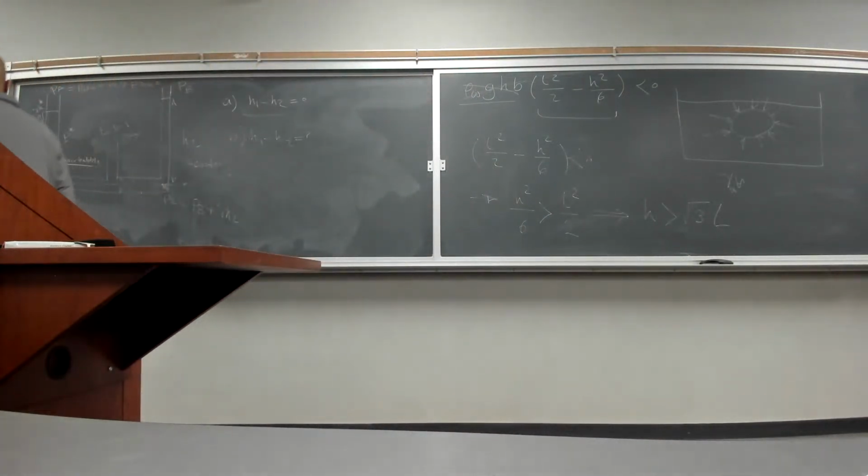Okay. Can we say this air bubble is immersed inside this fluid? It is definitely immersed inside that fluid. So the force that the fluid, the water, is exerting on this air bubble is going to be gamma of water multiplied by the volume of this air bubble.